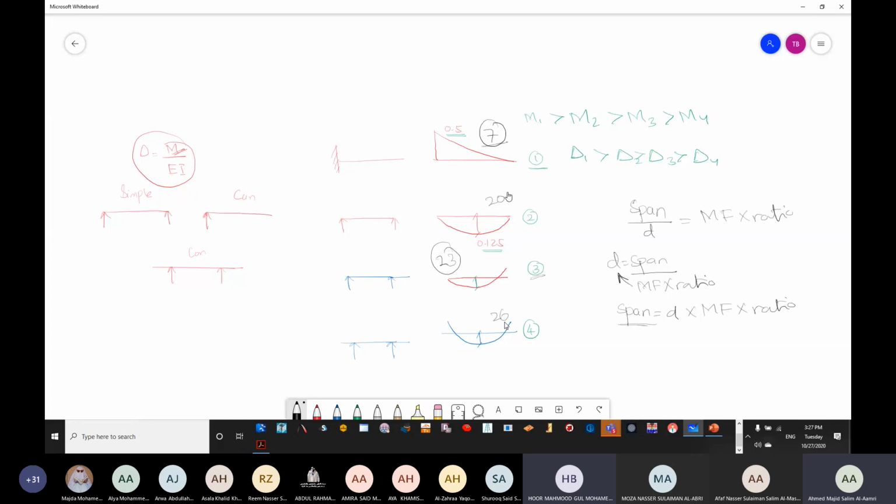And the question, Sir, is that also for the one-way slab, for everything, if you're having cases like one side continuous and another side discontinuous, so it will be like that. For the one-way slab, it is also drawn in the shorter direction, right? The concept of deflection is the same whether you are talking about one way or two way. Because actually, if you see, cantilever is only a one-way case. It will never be a two-way case. Okay, so the concept of deflection is the same, whether it's one way or two way.